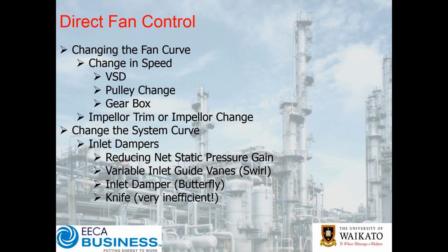Now you can do this quite efficiently with variable inlet guide vanes. If they're installed and actuated correctly, they can get very good performance. Certainly at the lower end, you'll start to lose a little bit in efficiency, at 30% of full load, 40% of full load, but up at 70-80% they're going to perform very, very well.